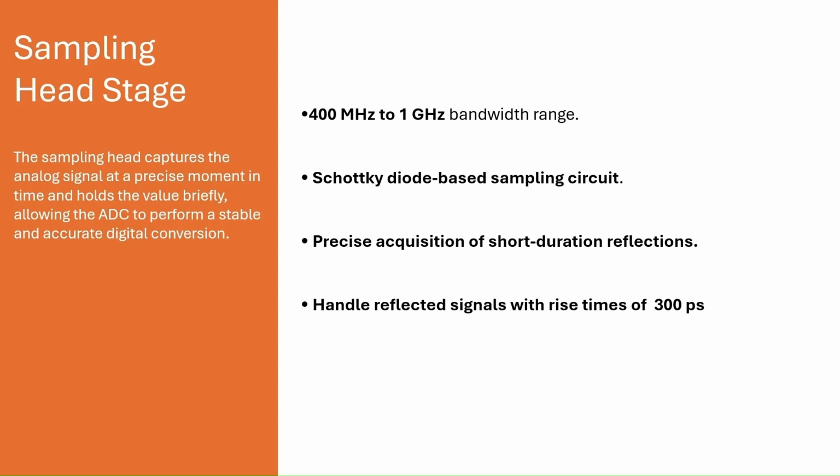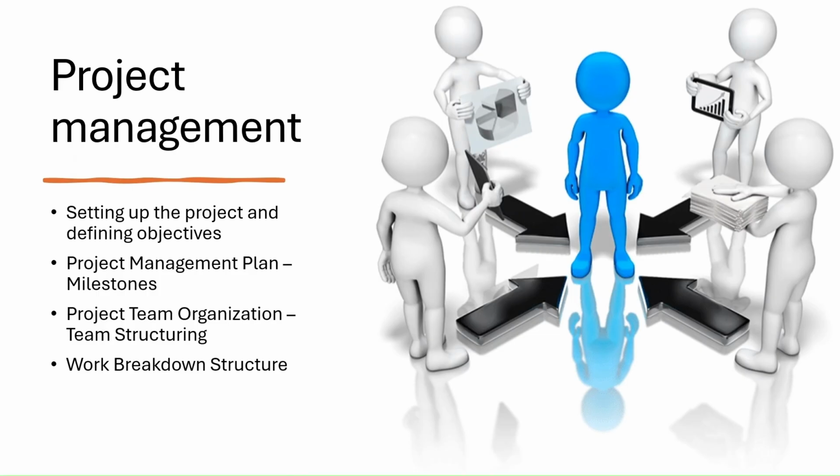We are using a Schottky diode based sampling circuit. This is helping us a lot with the precision. We are looking for precise acquisition of short duration reflections and to handle reflection signals with a rise time of 300 picoseconds.